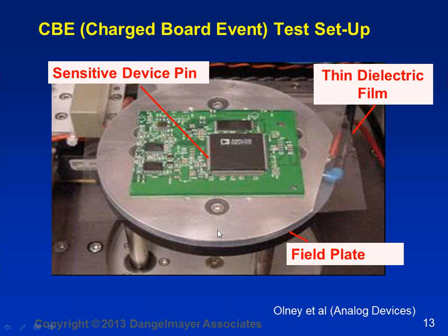Here is a case study done by Analog Devices and Andrew Olney and his team there at Analog ADI. The reason they undertook this study was an unacceptably high failure rate or return rate from customers. When they did their diagnostics in the FA lab, the signatures that they saw indicated electrical overstress. The damage was very extensive and inconsistent with ESD, or so we thought at the time.